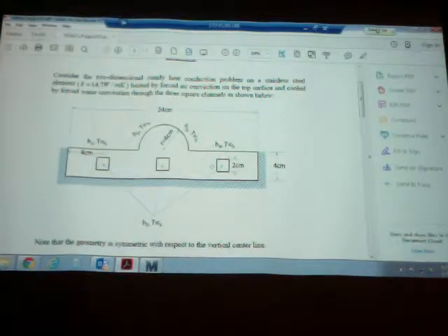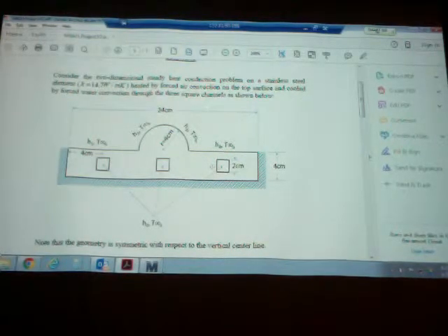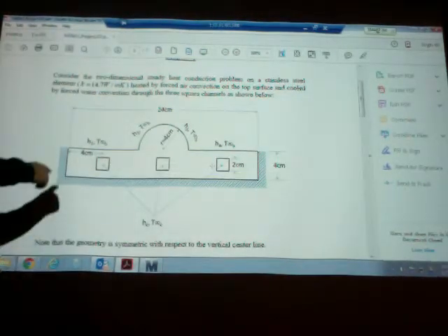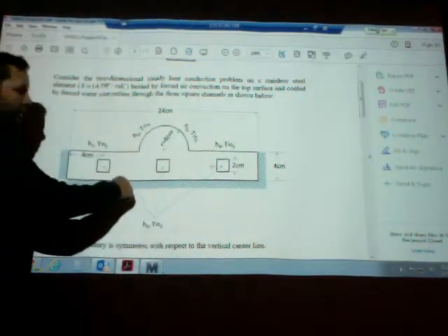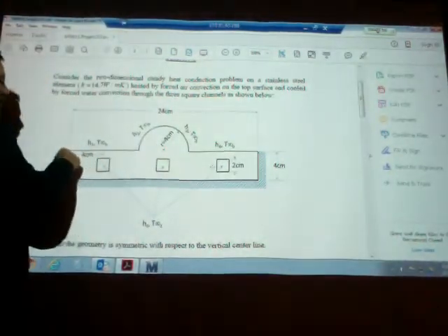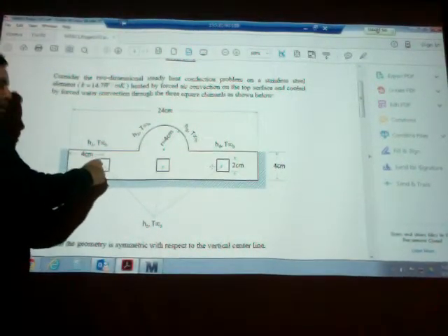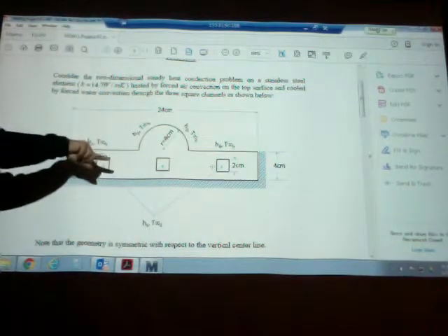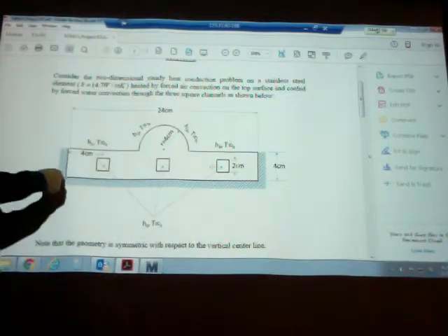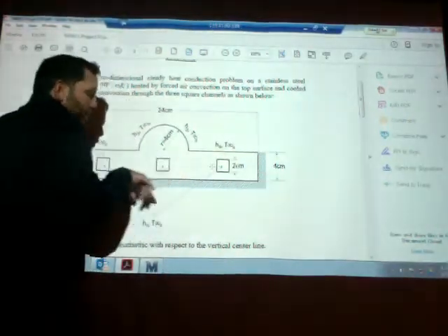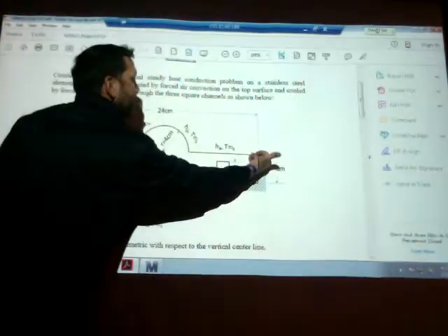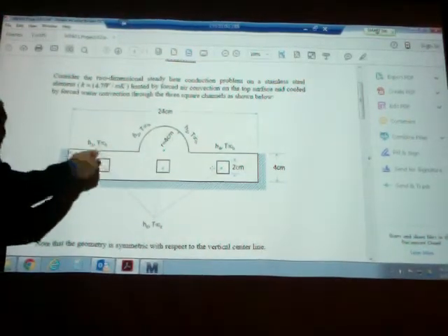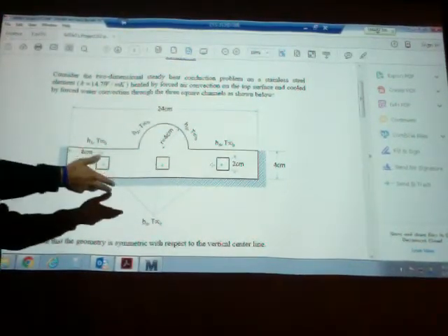All right? So the assumption here is that this is insulated here, or embedded, and this is your domain, this is your boundary. It goes like this, like this, like this, and like this. And the boundary continues here. However, here, because this is a hole, you have to go clockwise so that the normal points inside. You define your boundary here counterclockwise so that the normal always points outside. And when you get to a hole like this, you have to go clockwise so that the normal points inside the hole, which means outside the domain. Right?